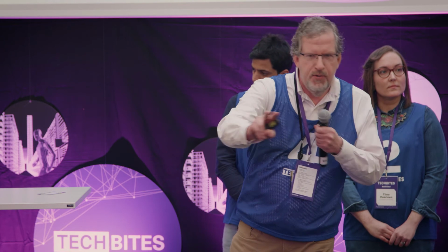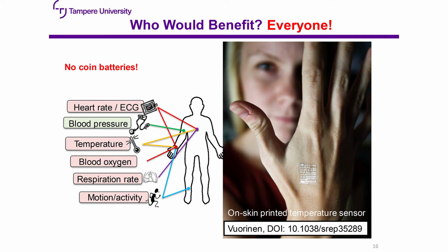So here is the equation for a transistor. I'm not going to lecture to you. I lecture to my students. But most people are looking for high mobility materials, and I'm arguing that we can generate the same performance by increasing the capacitance by using a very clever high-K dielectric. This has been done in Intel microprocessors, and we're trying to replicate it in this modality. So we want energy thrifty for these energy constrained systems.